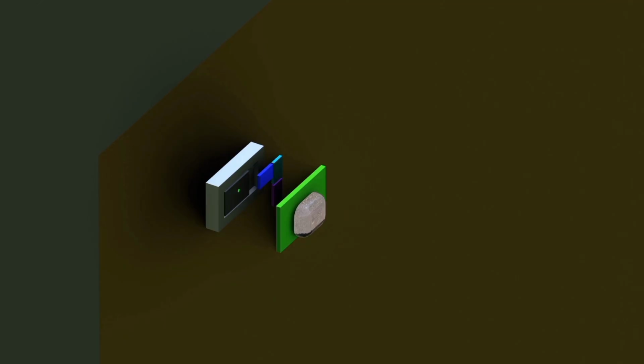Each photodetector consists of a silicon substrate, a potential well, and a photodiode that measures incoming photons. The color filter ensures that only specific wavelengths of light reach the photodiode. The transistors and internal buses amplify and transmit the electrical signal generated.